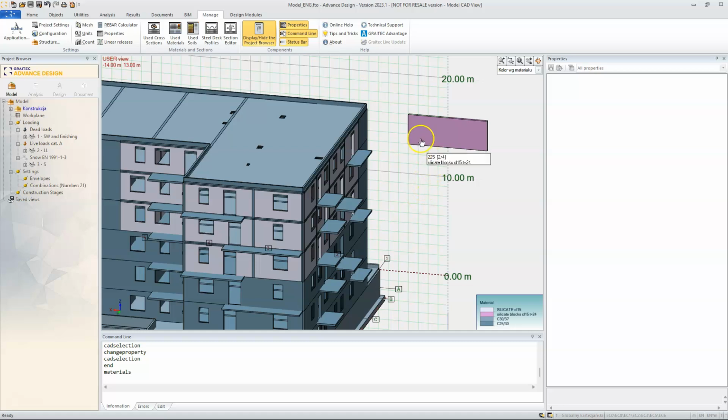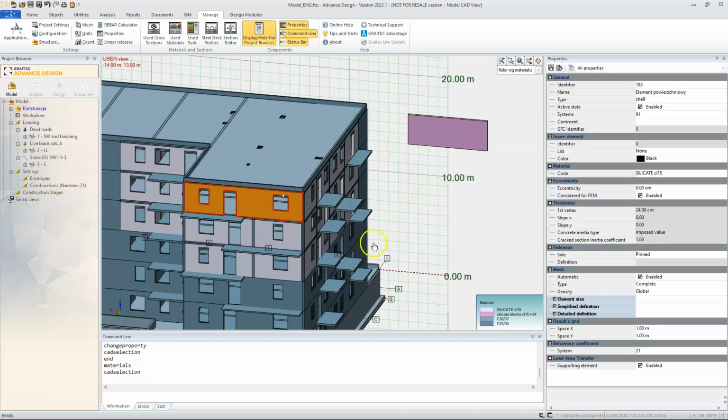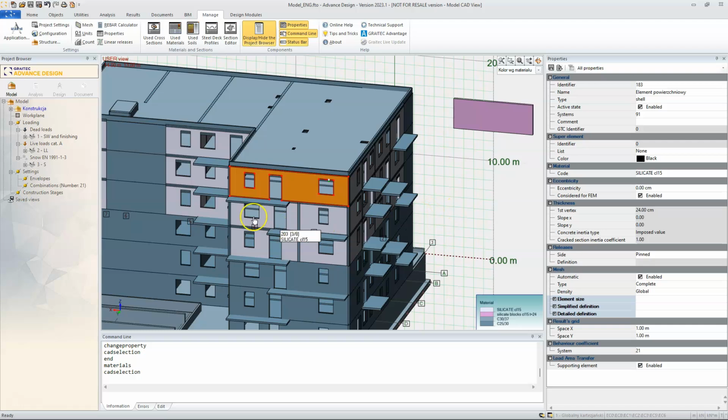If it comes to modeling of masonry walls, what we'll have to design is actually some panels. So usually between the openings, we will design each panel separately. But you don't have to divide the element to make them separate.